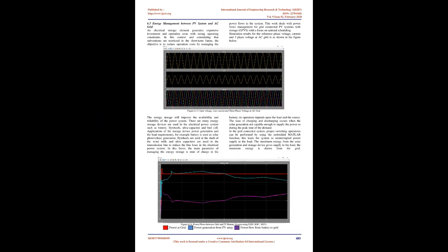6.3 Battery module. The parameters of the equivalent circuit can be modified to represent a particular battery type, based on its discharge characteristics. A typical discharge curve is composed of 3 sections, as shown in the figure. The first section represents the exponential voltage drop when the battery is charged. Depending on the battery type, this area is more or less wide. The second section represents the charge that can be extracted from the battery until the voltage drops below the battery nominal voltage. Finally, the third section represents the total discharge of the battery, when the voltage drops rapidly.